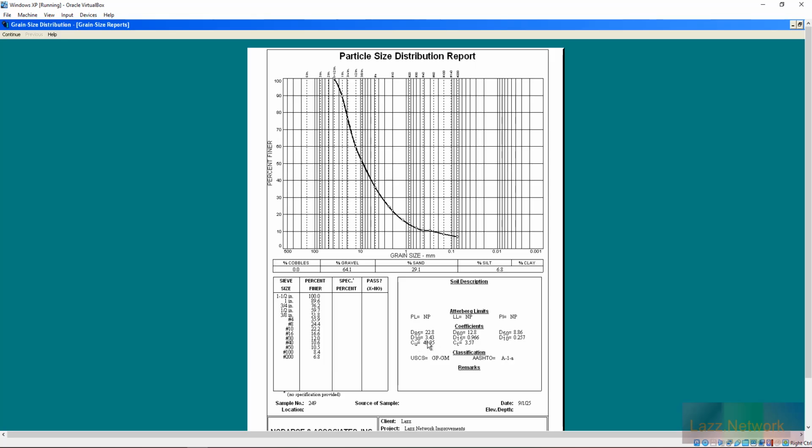This is 23.82, and then the CC should be 1.71. But I think the only reason why is because this had a hydrometer with it, which probably is what made it get up to well graded. I mean, don't get me wrong, the hydrometer doesn't look great because there's really no silts or particles to make the hydrometer float, so it just kind of drags on the ground.